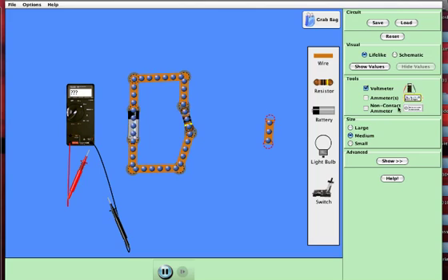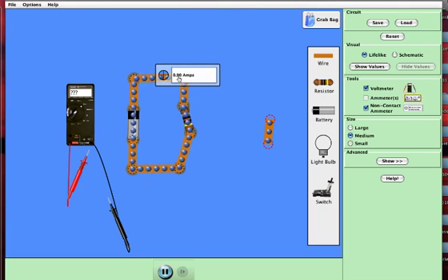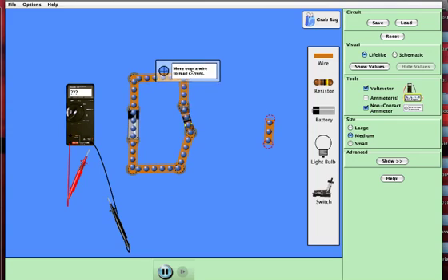So if I take a non-contact ammeter right here and move it over the wire, that means there are 0.9 coulombs of charge passing by this point every second. So 0.9 amps is 0.9 coulombs of charge passing through this point every second. This is what an ammeter does. The way that you really need to connect an ammeter to measure current, and let me drag it out here,